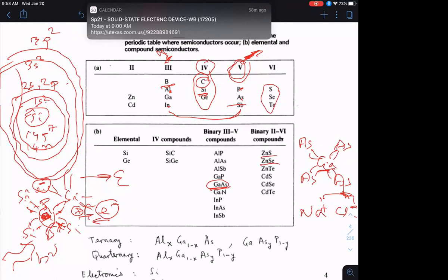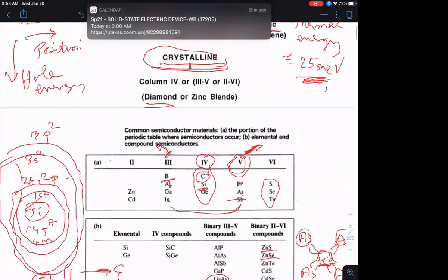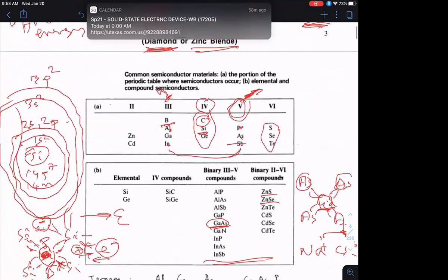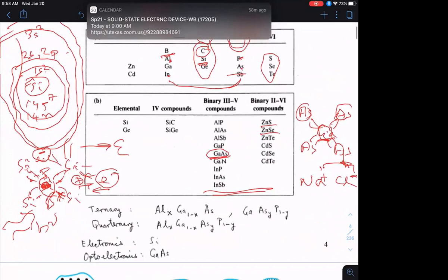Okay. So these lattice structures for these compound semiconductors have obviously 2 types of atoms in the crystal, unlike something like silicon or diamond, which is the same kind of atom everywhere, right? If it's the same kind of atom everywhere, those are sometimes called diamond structures, because that's what diamond is. It's all carbon atoms. But if it's 2 different types of elements, such as 3,5 or 2,6, and so on and so forth, those are called zinc blende structures. Okay, because zinc blende is a mineral in nature. I believe that's I think zinc selenide. I think that's a mineral in nature.